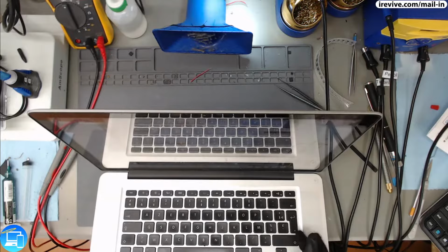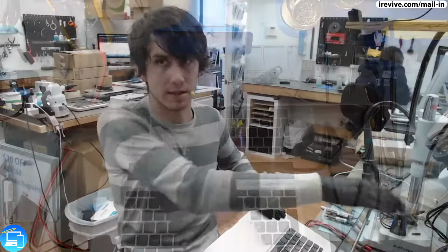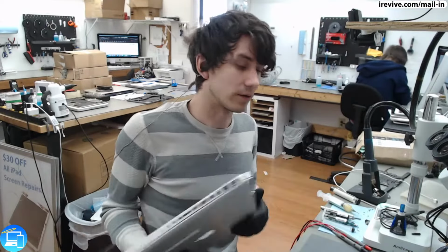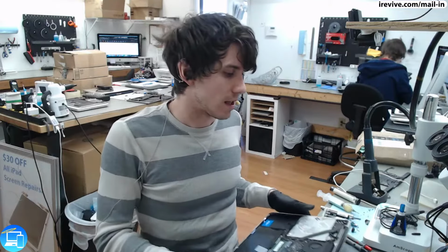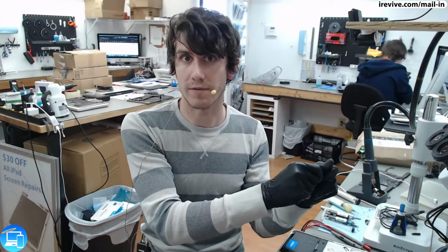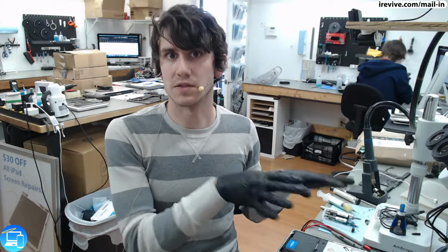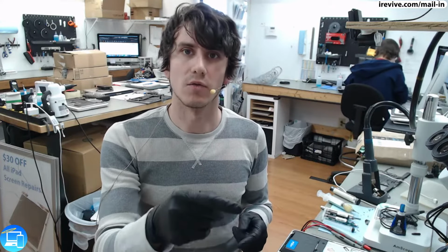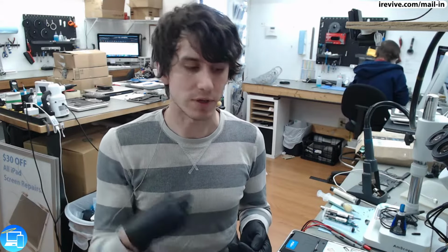So even though the AMD graphics card has failed, we've bypassed it. We're no longer using it. This is a fully working computer. The power supply going to the AMD graphics card is still present, and so even though this is turned off, the AMD graphics card is still getting power. So we want to disable that for 2 things. It's going to cut down on heating, because we don't need to heat up another processor if we're not using it, and it's also going to save on power consumption, so this is actually going to help out with battery life.